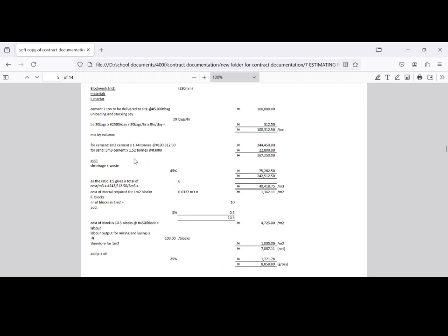6. Why? 1 cubic meter for cement, which is this, 5 cubic meters for sand, which is this. Add it together. That was how we got it. So now to get per cubic meter, remember this is in 6 cubic meters. We'll have to divide it by what? 6. So this total here divided by 6 will give us what? 40,475 per cubic meter.